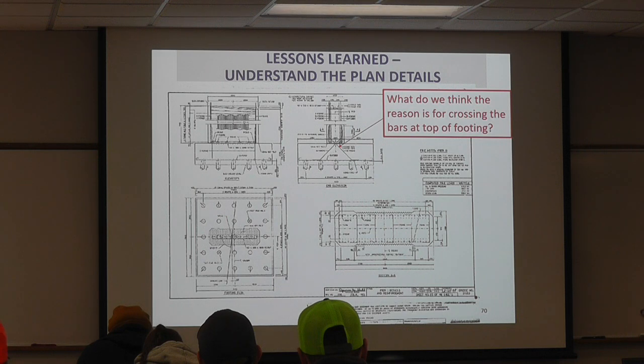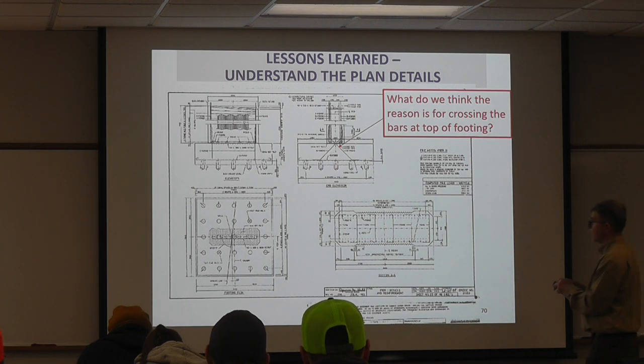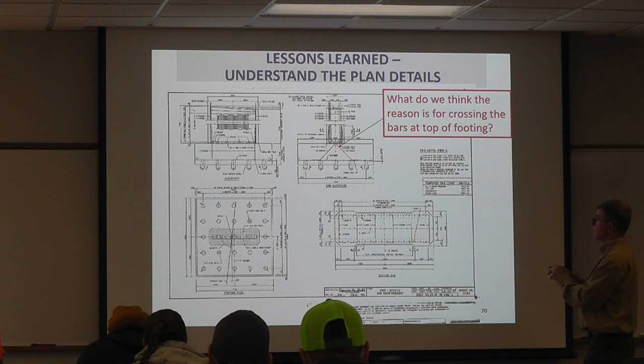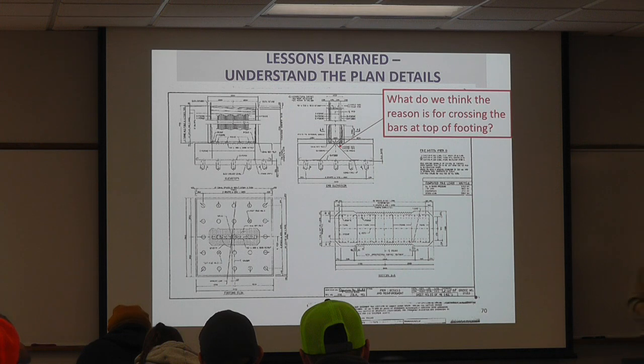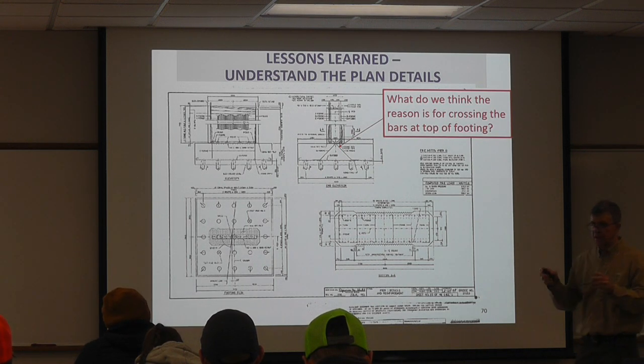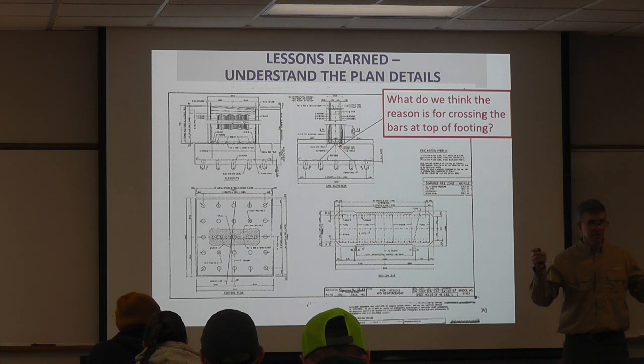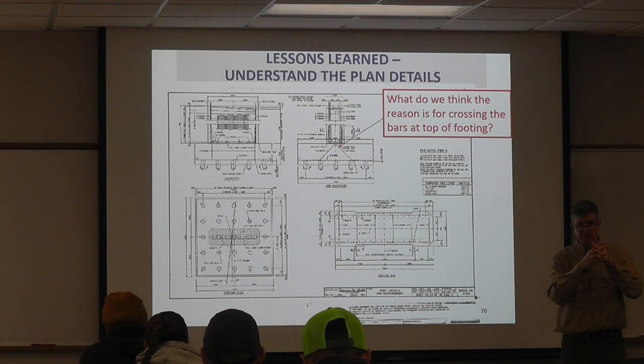And so we also then have bars that are crossing. This bar crosses and goes up the left side, this one goes up the right side. Everything crosses here. There's no bars on the outside of that pier. Who might have a reason to think why we would just cross the bars at the top of the footing to go into the column, and there's none on the outside? Okay. It's load transfer, and more than load transfer, it's...